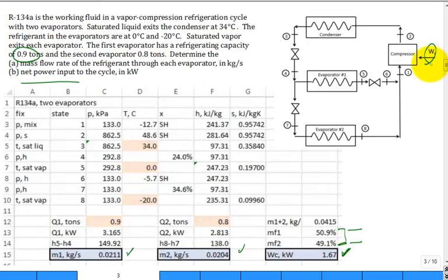Do all these values look good? Why did I color code this one, this one, this one? They were pretty much given. Yeah. So somebody comes in and says, no, it doesn't come out at 34 degrees C, it comes out at 36 degrees C. Well, I can change the code and it'll percolate through and redo the numbers. Oh, I don't want this evaporator to be 0, I want it to be -5, and I want this to be -25. Okay, fine. It'll change, and that's the beauty of the software.